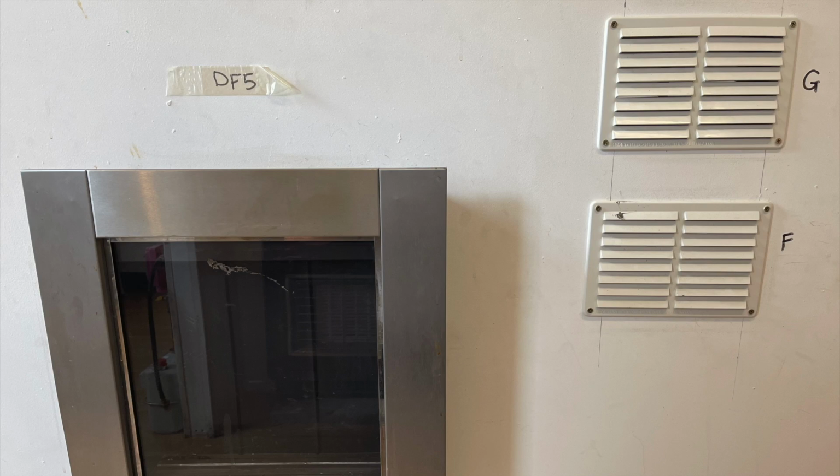Now this picture represents you going to do a landlord's report, and you find there is a flueless space heater. Now the flueless space heater passes all its tests, including its flue gas analyser test, but you find this ventilation, which is also the correct ventilation, installed in this location in close proximity to this flueless space heater. So how are we going to classify this?